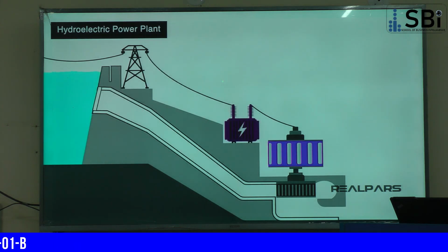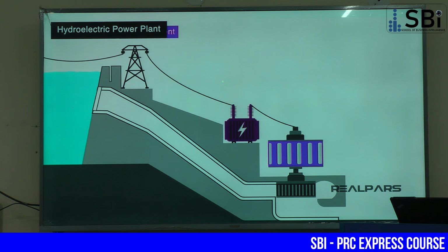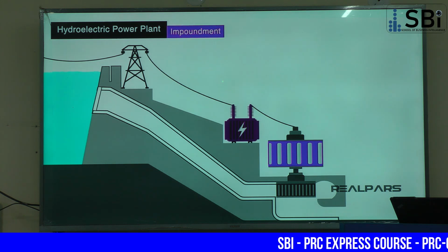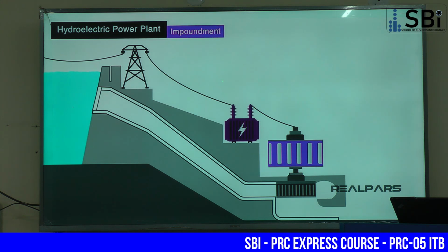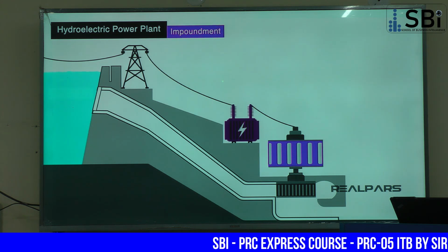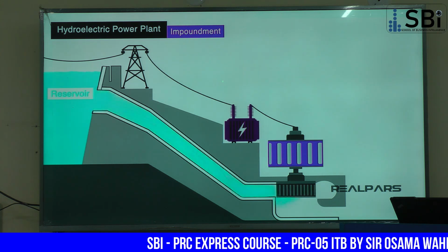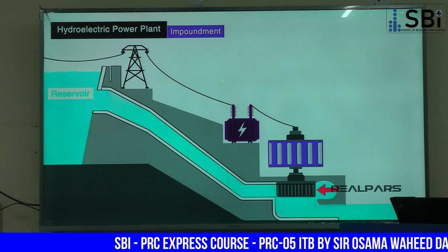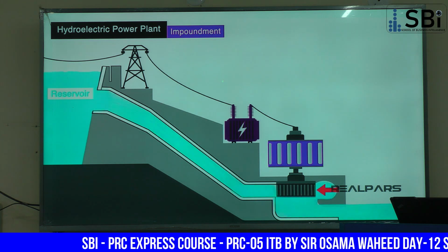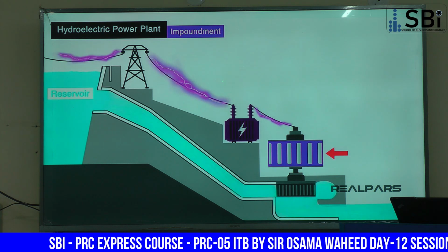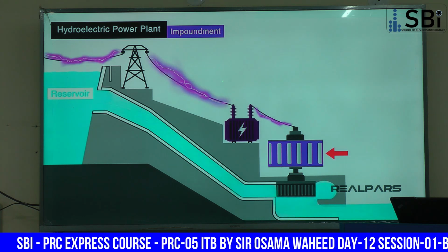Hydroelectric power plants generate power by converting the force of water to turn large generators. Hydroelectric power plants fall into 3 different categories. First up is impoundment. An impoundment facility typically uses a store of river water from a dam in a reservoir. When water is released from the reservoir, it flows through a turbine which generates motion. This turning motion activates a generator to produce electricity.